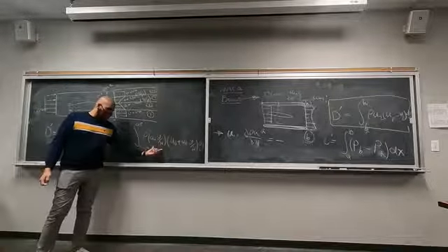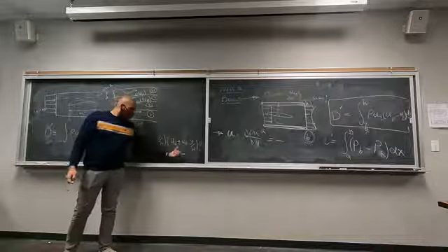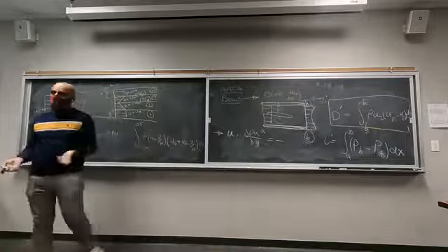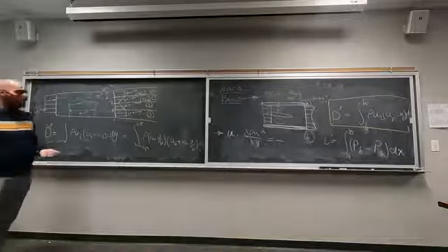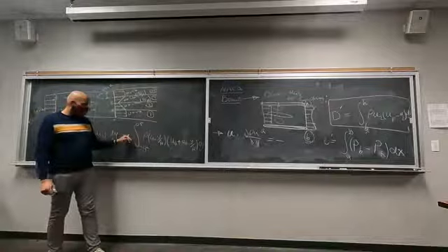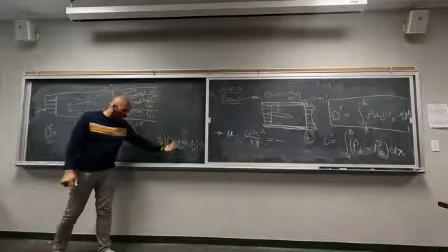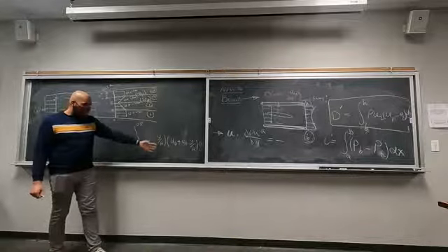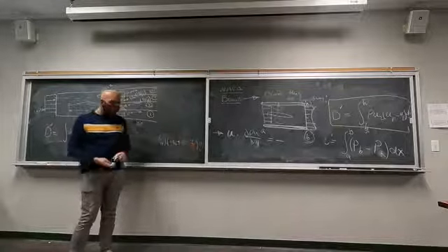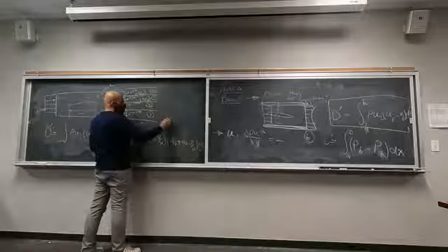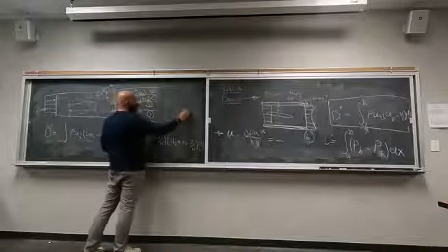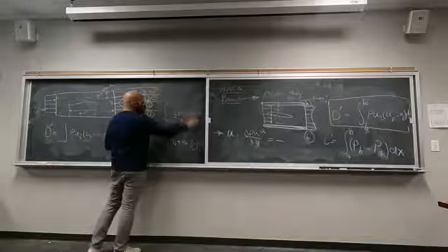You can multiply these two parentheses together. U infinity and rho are constant if we are dealing with the incompressible flow. Rho is constant, so we can take all of these out. We're going to end up with rho u infinity squared, right? Because we can take a u infinity from here as well. Negative y over h multiplied by 1 plus y over h. Does this make sense? So I'm just going to write this here, the integral from 0.25 to 0.5 of negative y over h times 1 plus y over h dy.